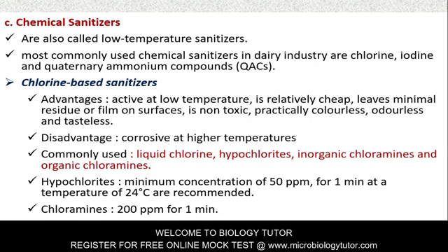Chlorine based sanitizers. Advantages of chlorine based sanitizers: active at very low temperature, is relatively cheap, leaves minimal residue or film on surfaces. It is non-toxic, practically colorless, odorless and tasteless. Disadvantage: corrosive at higher temperatures. Commonly used: liquid chlorine, hypochlorites, inorganic chloramines and organic chloramines are used.